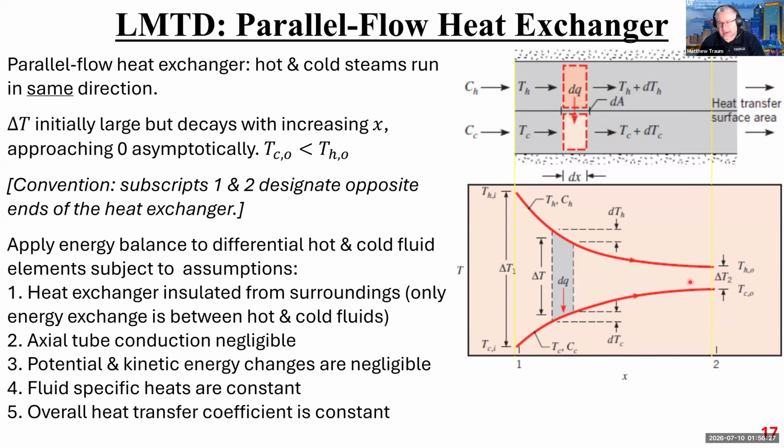At an infinitely long heat exchanger, they're the same temperature, but always in the real world, T sub H at the outlet is greater than T sub C at the outlet. And we'll see for the counterflow heat exchanger that's different, but it's an important thing to know for parallel flow heat exchangers.